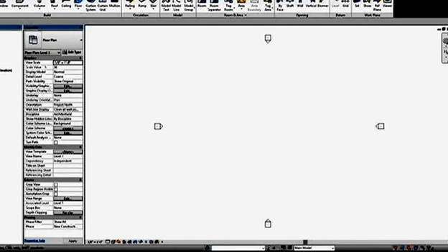All right, the next thing we're going to cover is this toolbar up here just to the right of the R. This is called the Quick Access Toolbar. And kind of like the view toolbar that I just showed you below, it's a series of icons of commonly used tools in Revit. If you use a tool quite often, you can add it to the quick access toolbar, and then it's just one click rather than trying to figure out what tab it's under and then selecting the correct tool. So it makes drafting a little faster and easier in the long run.